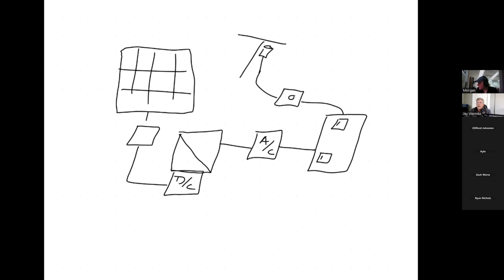And the reason for that is when the first responders come and they pull the meter, if there's a fire at the house, there'll be a label on that meter saying, hey, there's another source of energy here at this location. They're going to look around, and within 10 feet, they're going to see the AC disconnect, and it's labeled, this is the main disconnect for the PV array. So that's the whole reason why it has to be located where it is, because typically first responders and clearly the utility know where your meter is. So that's where they're going to go to make sure there's no power in the house.